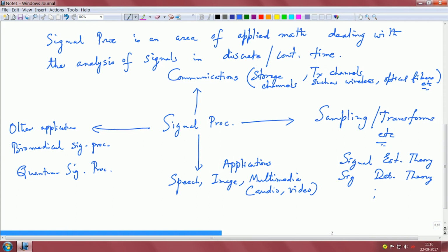communications side. So imagine you are taking your data bits and then you are modulating these data bits and then transmitting them over, say, a wireless channel. You are transmitting them over air. So it is basically analog, and then you have to do some filtering when you receive the signal, and once you do the filtering and removing noise and cancelling some of these nonlinear effects, you will have to basically do some sampling, right.